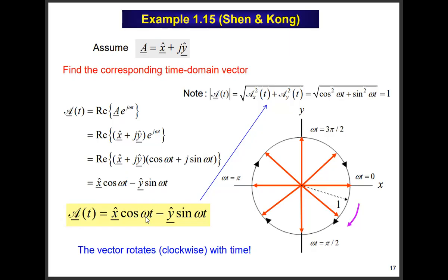Now you may remember this trick. Sine of x is cosine of x minus pi over 2. Remember that trick? So this would be cosine omega t minus pi over 2. Or again, 1 out in front, times cosine omega t minus pi over 2. Okay, so what's the magnitude? What's the phase angle? Okay, so the phasor would be 1 e to the minus j pi over 2.